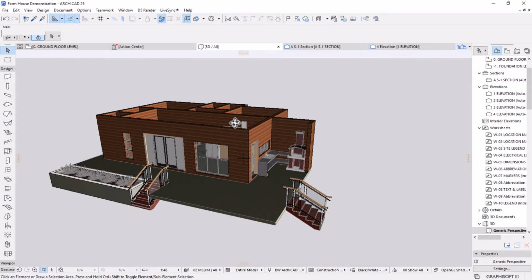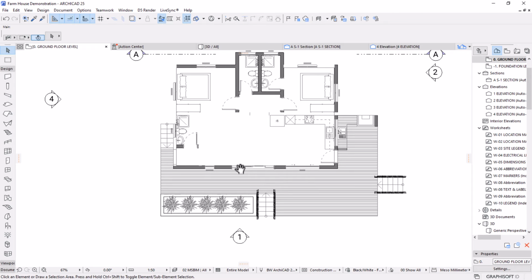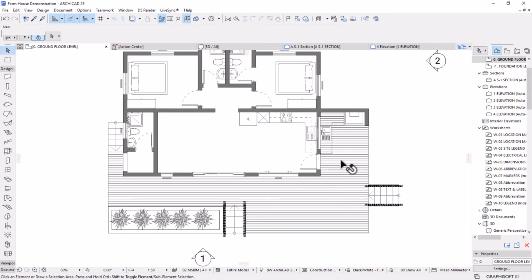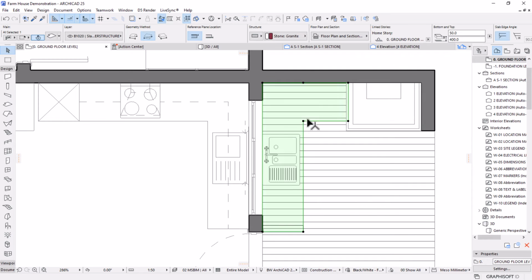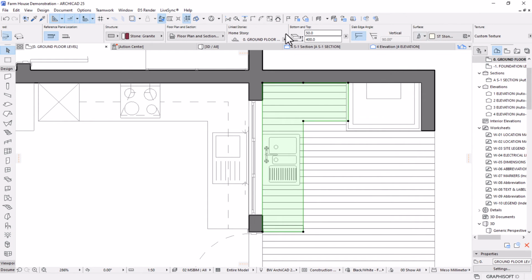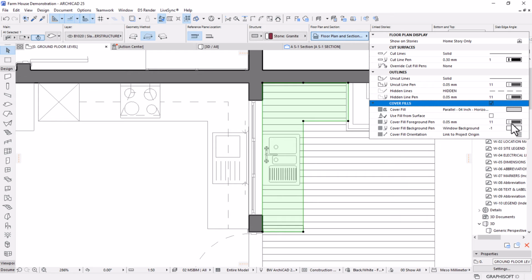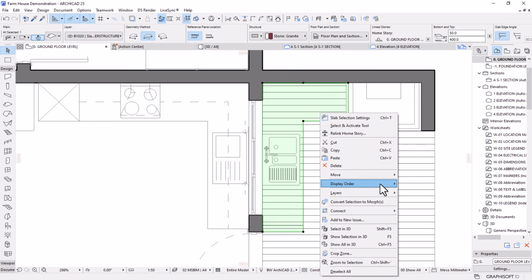Okay, I can get rid of this solid element operation window and then go back to the ground and complete the remaining furniture for the dining, lounge, and then the outdoor lounge and the entertainment side. So we still have a problem of material underneath interfering with our elements. So I'm going to select this, and instead of not using cover fill in the floor plan section, I'm going to use the cover fill, but this time around it's going to be just empty, and then I'll use that.